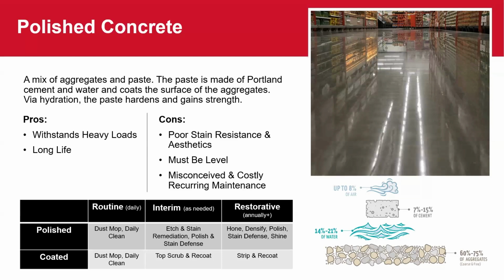They're all different, especially if they were not poured to be polished. Today, if you know you're going to polish your concrete floor, the mix that they use is significantly different than if you're not going to polish that floor, with the aggregates and the type of cement and the water and all that they put in there.